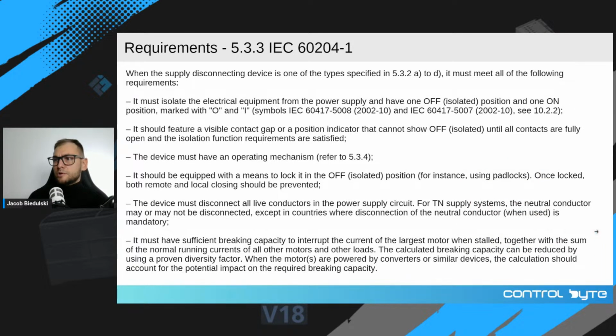We have some more requirements in the standard. For example, it must have sufficient breaking capacity to interrupt the current of the largest motor when stalled.